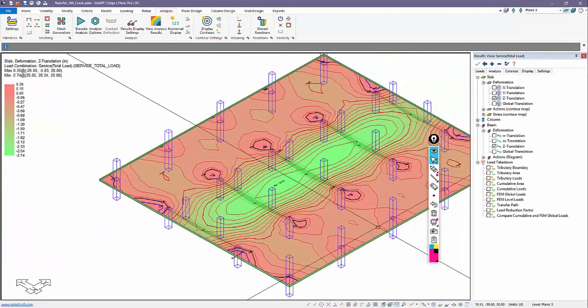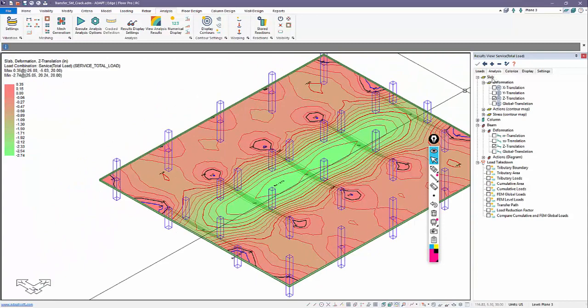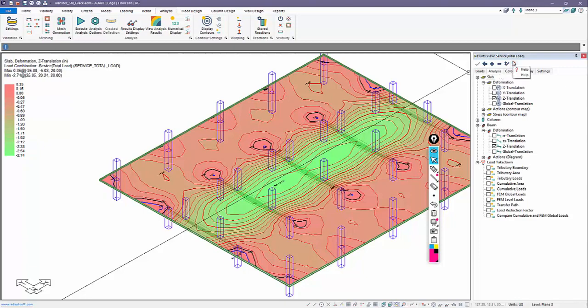So we can check deflections. These are immediate elastic deflections based on the service total and service sustain case. These are not cracked deflections that the program has checked. So in this case, we artificially crack it by applying the modifier, check the deflection. This also does not include long-term. We would have to use some multipliers potentially to predict the long-term under an artificially cracked state.